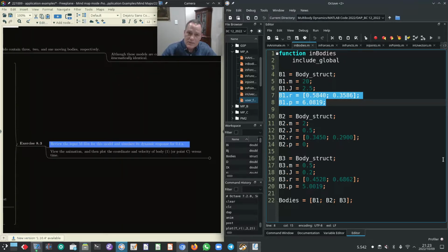And as we saw with the double A-arm suspension, depending on the initial positions and velocities that you specify, when you correct the initial conditions, it finds a solution close to the positions and orientations that you specify, and that satisfies the position and velocity constraint equations.